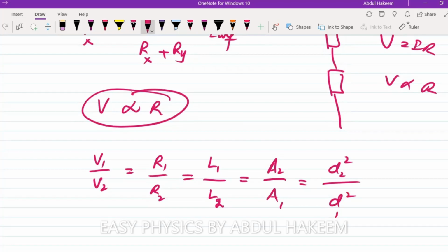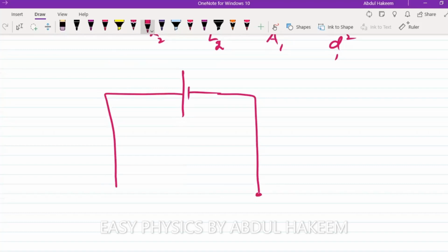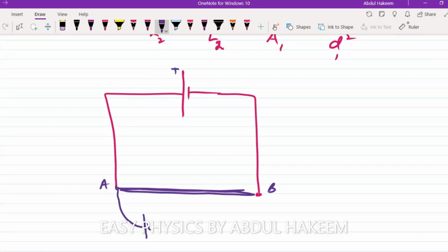Now, in the potentiometer, this is the resistance wire, A and B. So do remember, the unknown cell must be connected in parallel to the previous one. So this is positive, this is positive. And here, with a galvanometer or ammeter, we will find the balance point, meaning the point at which the meter reads 0. So suppose this is the balance point, the total length of the wire is L, and the balance point length is X.